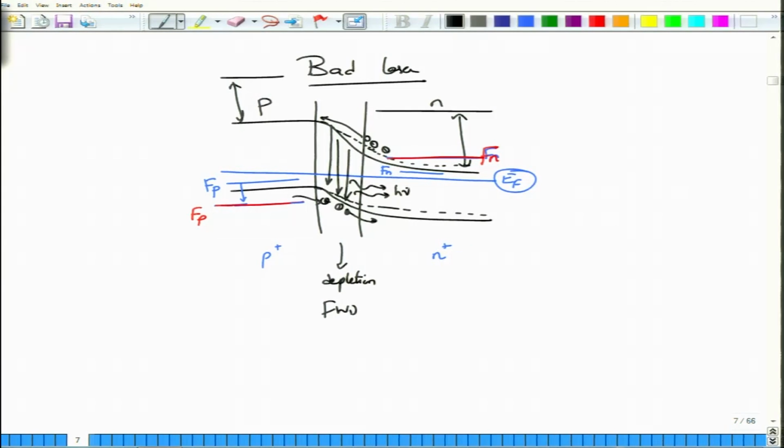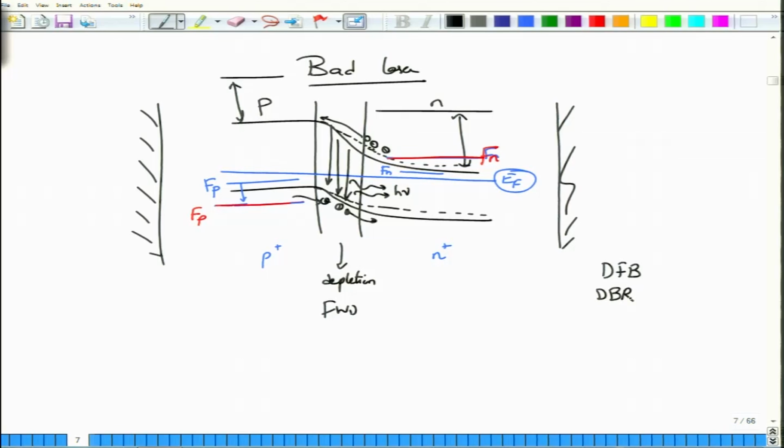Of course, this is just the emission part. You have to support this semiconductor with optical feedback. It is not done by putting a mirror as shown. I will tell you a couple of feedback structures and how they are done. They are usually done in the form of what are called DFB or DBR structures, where we embed a grating inside the material, and this grating gives you wavelength selectivity, because remember the spread of the emission cross section of a semiconductor is actually quite wide.